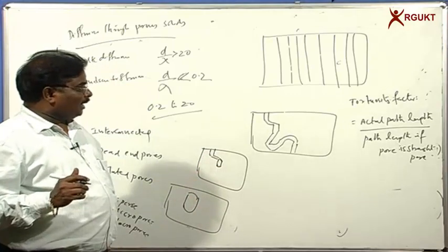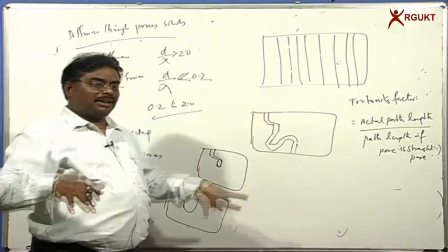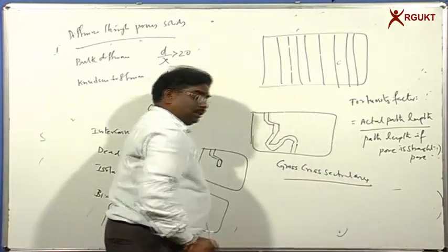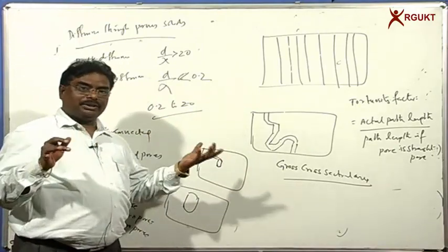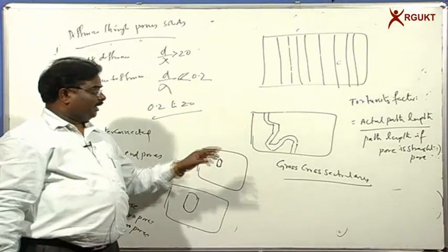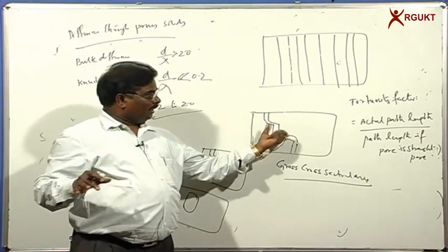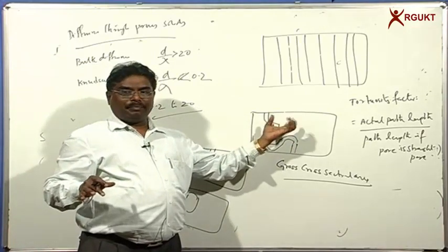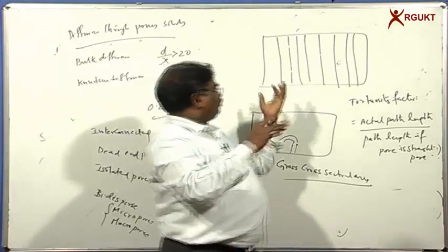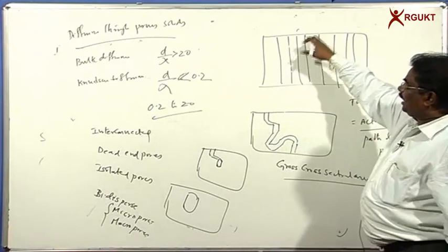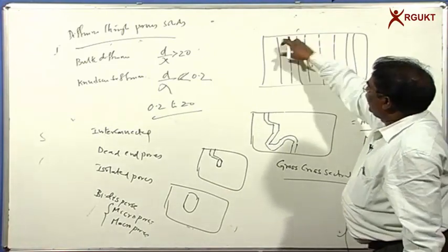So we are going to calculate flux based on the cross section area. Do you understand or not? What we are talking about: in the case of simple fluids, we know the surface area. But when you are talking about porous media, we have a big matrix. The whole matrix doesn't have pores. Some parts of the matrix have pores, some parts do not, and it is not so simple to calculate the fluxes. It is not so simple to calculate the area for the flow,